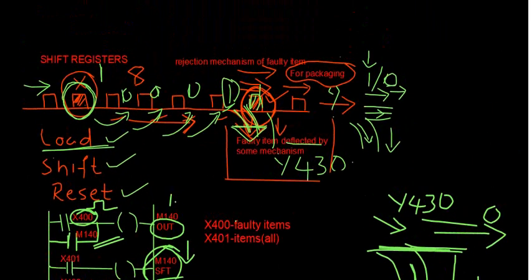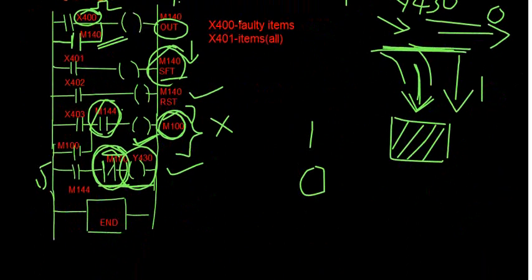You start from your LD X400, then OUT M140, right? So then again out, or okay, before that you have this M140 as the latch here. So if you want, we will write the instructions.